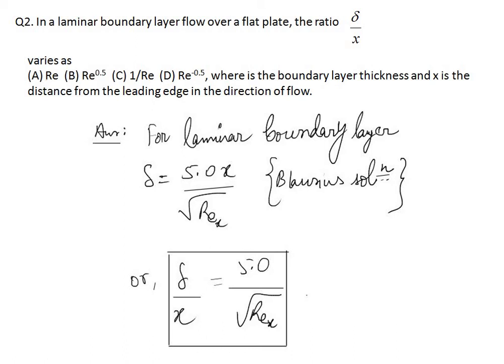When a fluid flows over a flat plate, the fluid element near the surface has a velocity of 0, which is called the no slip condition. There the skin friction is the highest. Due to that, velocity adjacent to the surface becomes zero, and as we move away from the surface, the velocity approaches the bulk flow velocity.